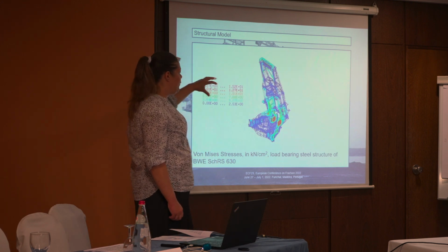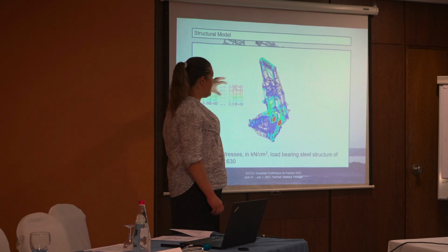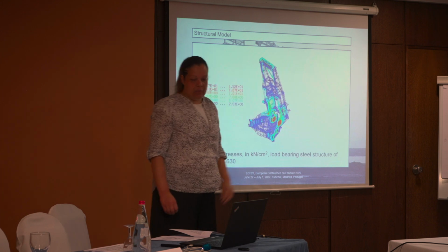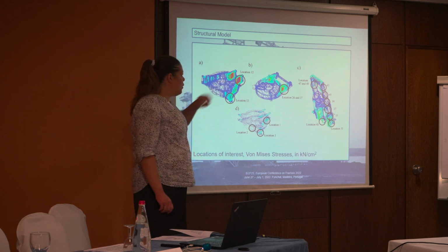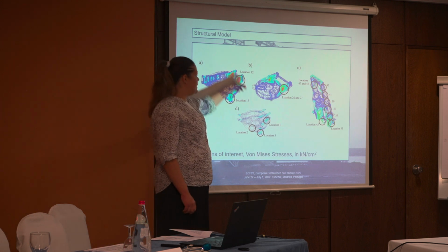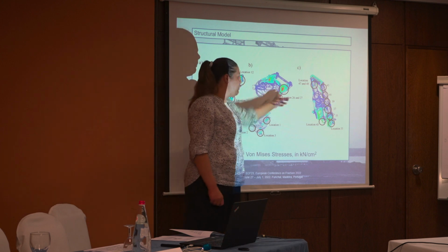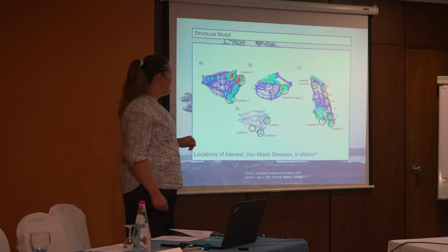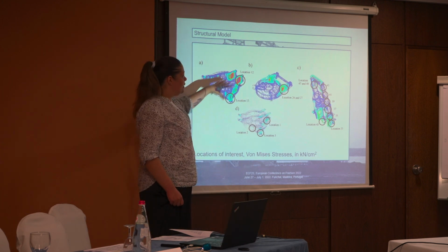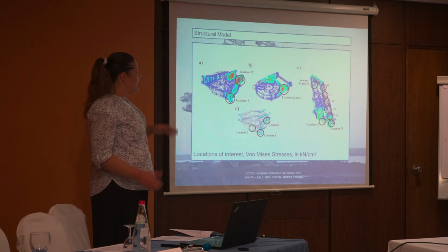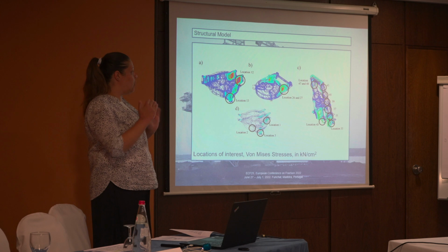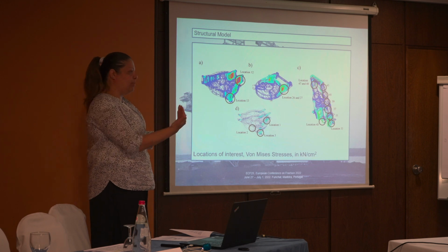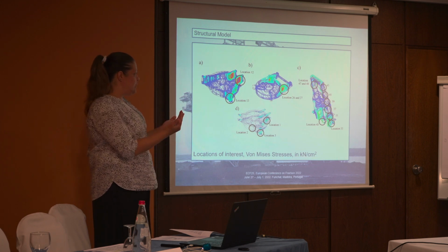So we had 50 functional zones, and in them we got stress values. Here you can see all the zones. This is, for instance, the undercarriage. This is the slewing platform, and those are pylons. And both undercarriage and slewing platform consist of two horizontal plates connected with vertical plates and with cylinders.